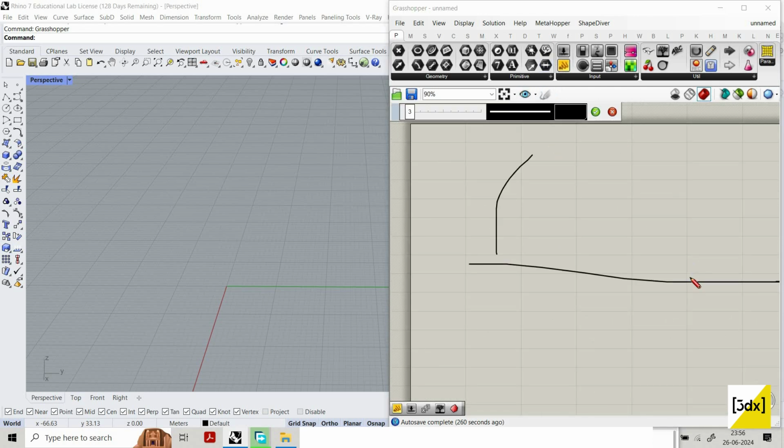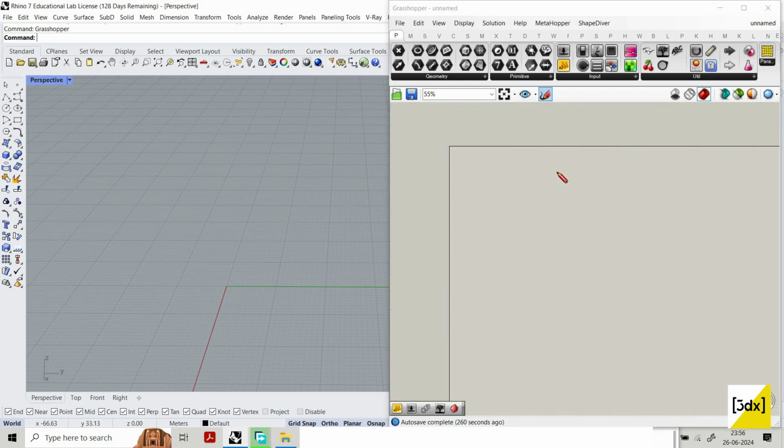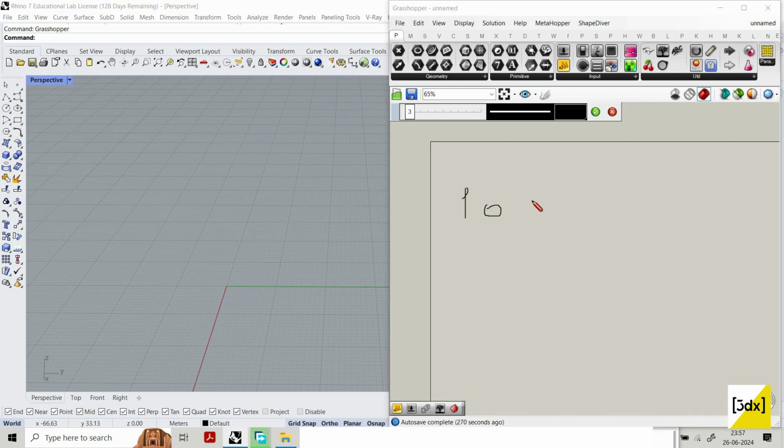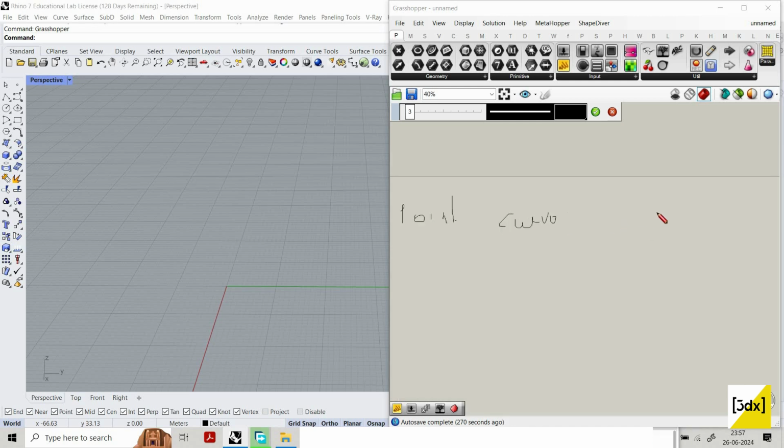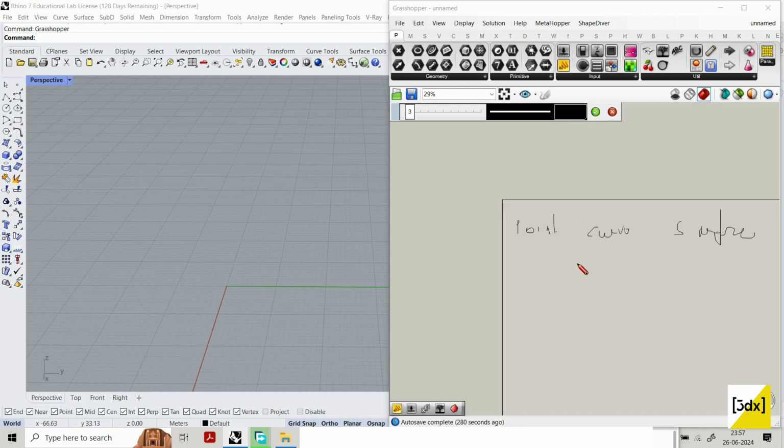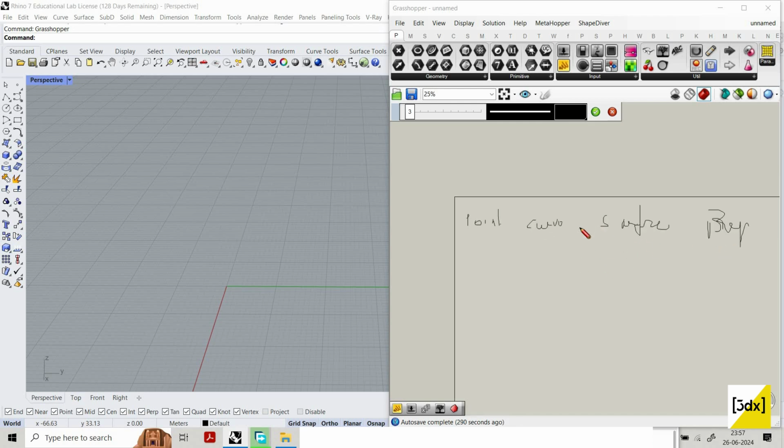So technically, we need to draw the dome. Okay. So like in Grasshopper, not only in Grasshopper, any model, let's have point, then curve, then surface, then mirror. So point is like every point. Curve is like polyline, polygon, NURBS curves, everything comes under curve. Surface is like planar, coplanar, curve surfaces, closed surface, and open surface. When it's a closed surface, then it becomes a solid or a brep. Brep sometimes is multiple surfaces joined together, which also comes under brep.